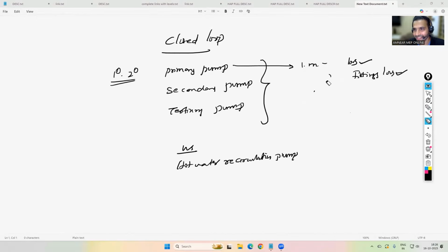Anyhow, those things are a very lengthy topic. In the chilled water side, we have already studied it; it will come to nearly 15-20 hours, right? Okay. When we are selecting the secondary pump, it is the same way. The secondary pump takes the water from the primary pump delivery side, or the chiller delivery side header, takes the suction, and then delivers through the building through the chilled water supply side, serves all the coils, and then comes back through the chilled water return until the primary pump suction.